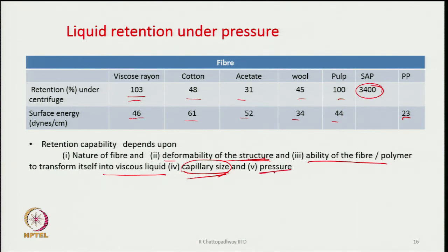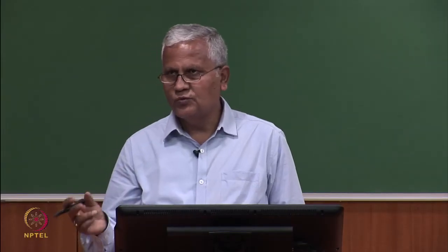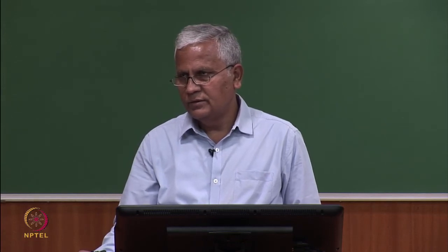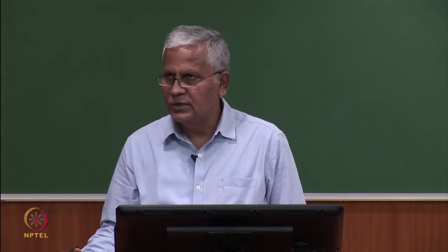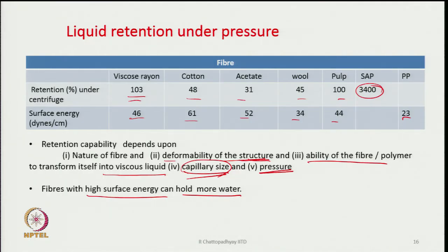Then comes the external pressure that we apply. If the pressure is less, more liquid will be retained. If the pressure is more, less liquid will be retained. That is how liquid retention will change. And fibers with high surface energy can hold more water. They will not allow the water to move out from the capillaries so easily. They will create resistance to the movement of the liquid flow. So, that way